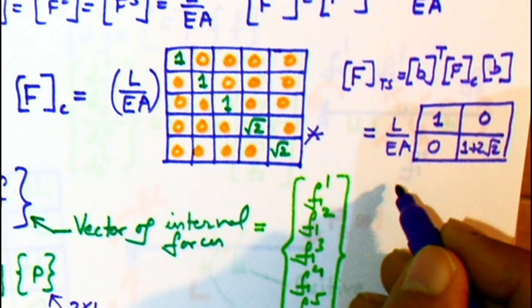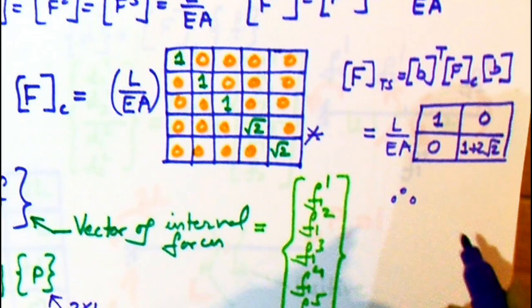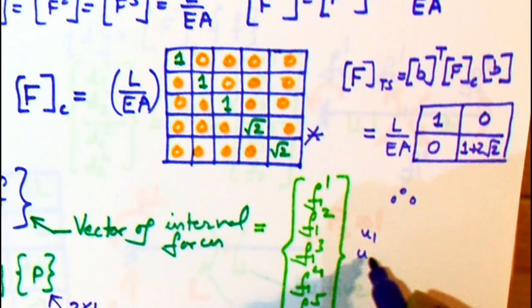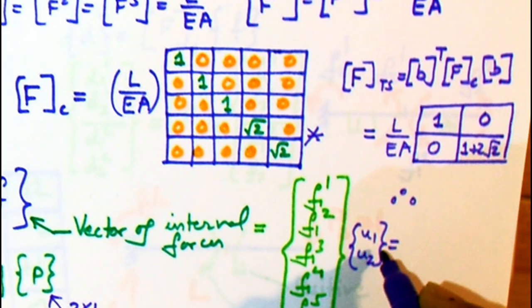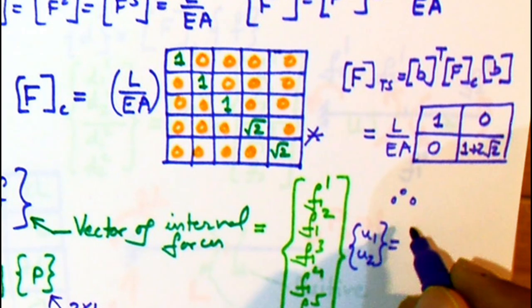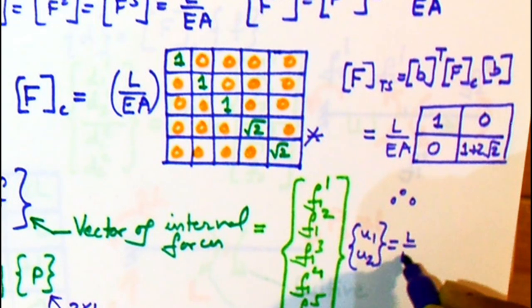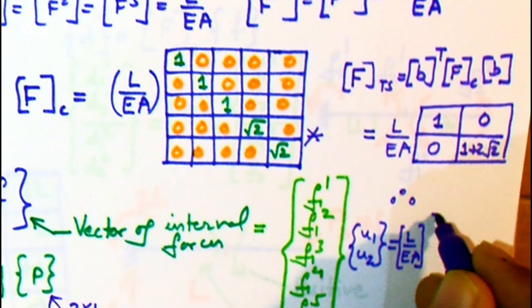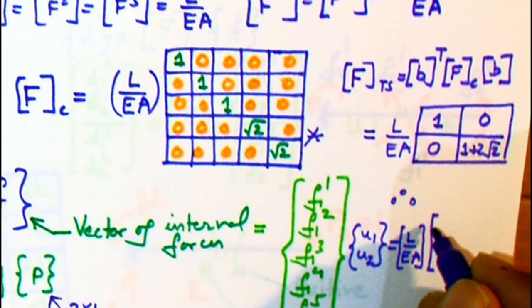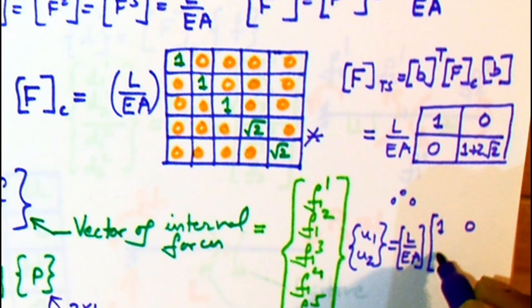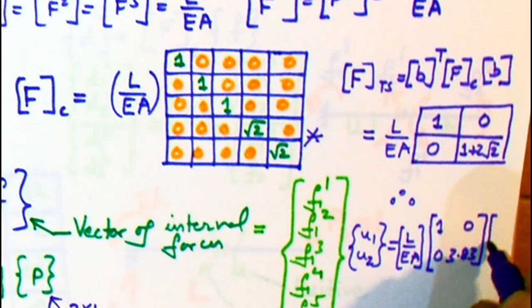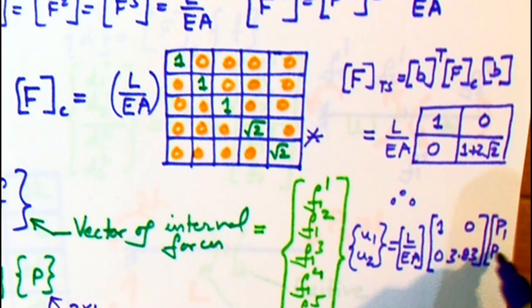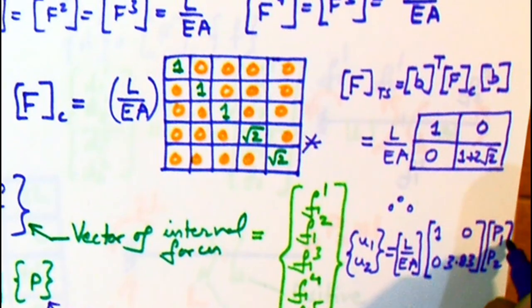Now we can use it to obtain the external displacements along P1 and P2, that is the displacements U1 and U2, which are shown. So this will be equal to FTS multiplied by P1, P2. So we have the answer. Similarly, we can find all the internal forces by just the product of B and P. So this step you can do yourself.